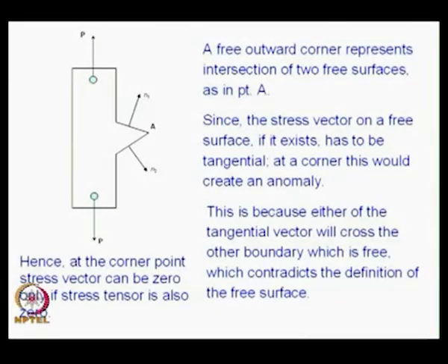Now, instead of the protrusion, if I have material removed here like a V groove, then this corner becomes singular, you will have very high stresses, and they are called re-entrant corners. When you are doing a course in fracture mechanics, you should also know about re-entrant corners. In fact, Williams eigenvalue solution was meant for that kind of V groove. When it is protruding out, when it is having a free surface, it is 0, when it is inside it is totally different.